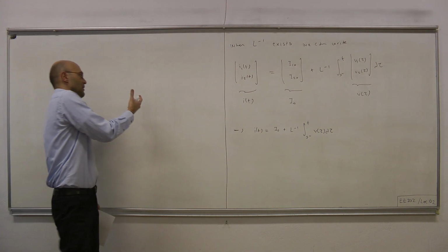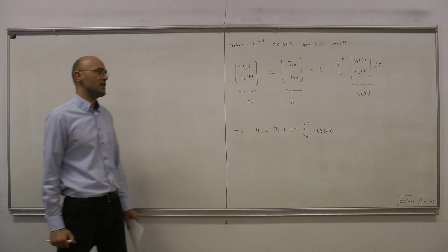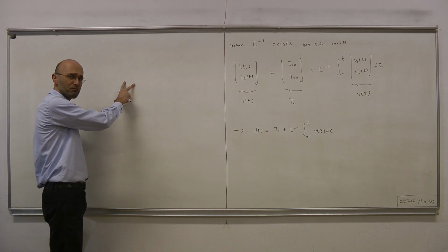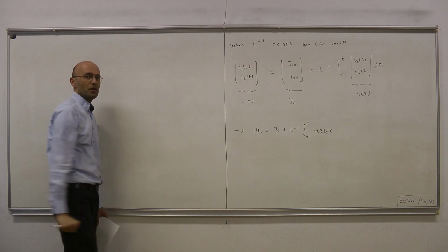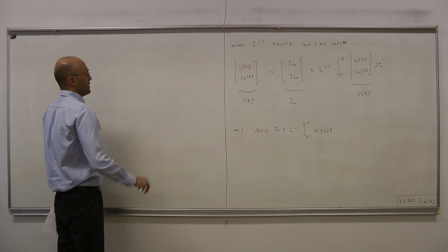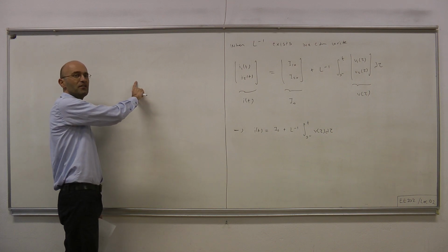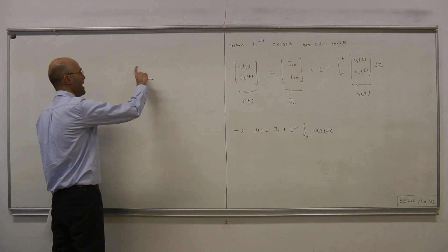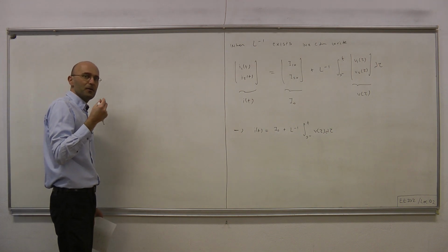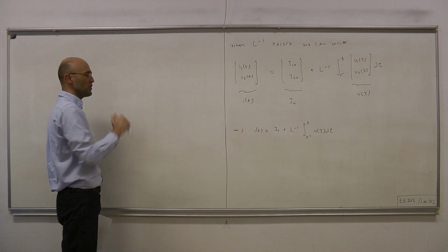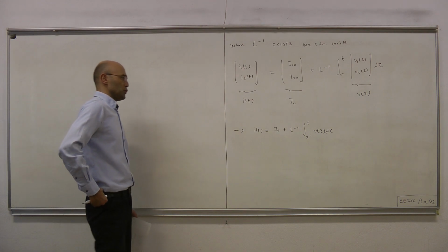Usually an inductor has an initial current or initial energy, likewise a capacitor has an initial voltage or initial energy, and when we put them on a circuit diagram, we have to write down somewhere that initial value, initial current or initial voltage. And we saw through initial condition models that we can represent that component, the capacitor, let's say, by an empty capacitor, and then express that initial stored energy through other means, which is possible through an independent voltage source or independent current source, and the dual case was also true for the inductor.